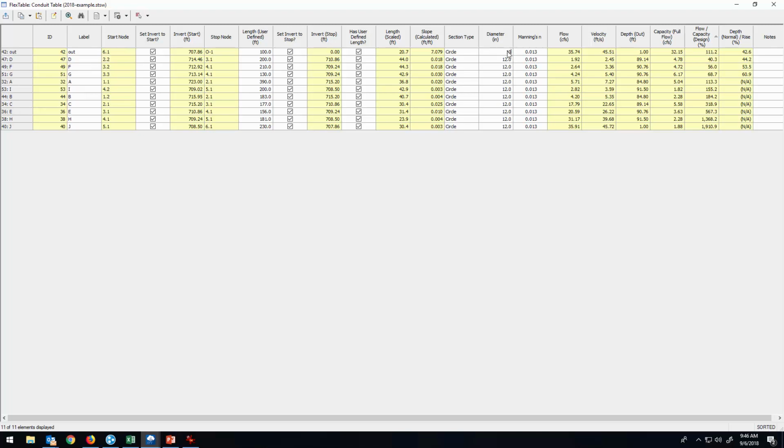So we could make that one 10-inch, and we're good. We'll try 10-inch for this one. That's good. Well, what about 8? 8's not going to do it. So it looks like 10 is probably going to be the smallest acceptable pipe diameter everywhere in our network, and that pipe G that I just optimized, 10 isn't enough, so we'll have to leave it at 12.